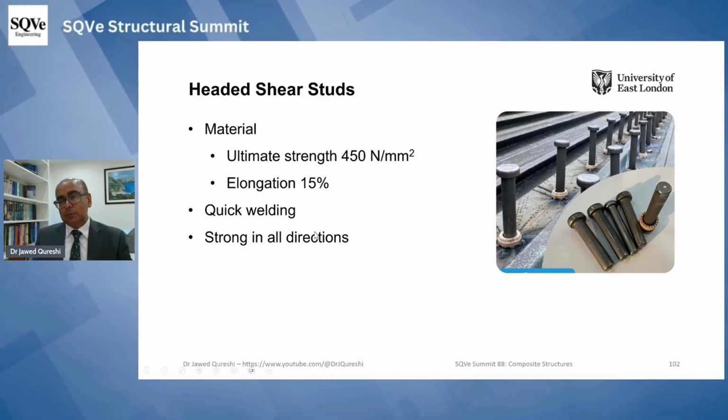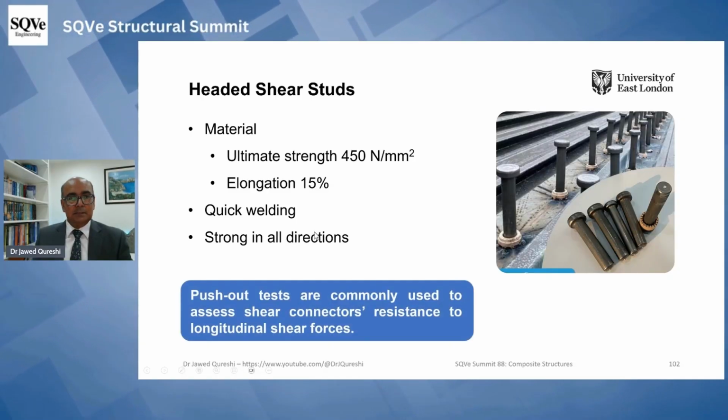This is very important. So in case of load reversal or in case of other loading, the beauty of these studs, round headed shear studs, is that they are equally strong in all directions. So in buildings, almost certainly you will use headed shear studs.